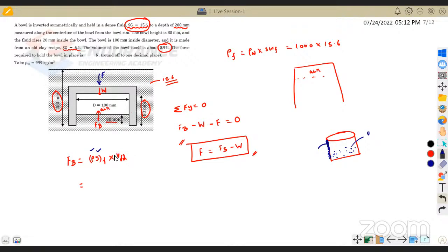But what is going to be the problem with the volume of the fluid displaced? See, the volume of the fluid displaced is nothing but the volume submerged, right? Now, what is all the volume which is getting submerged inside? Of course, the entire volume of the body got submerged inside. The volume of the body we already know, 0.9 liter. In addition to the volume of the bowl, one more thing also submerged. What is that? Air, exactly. This air is also submerged, right?